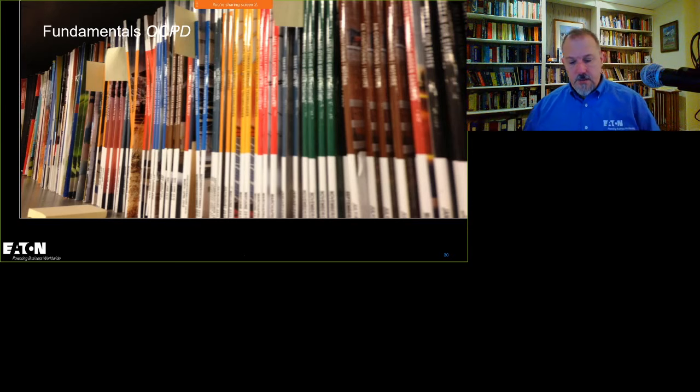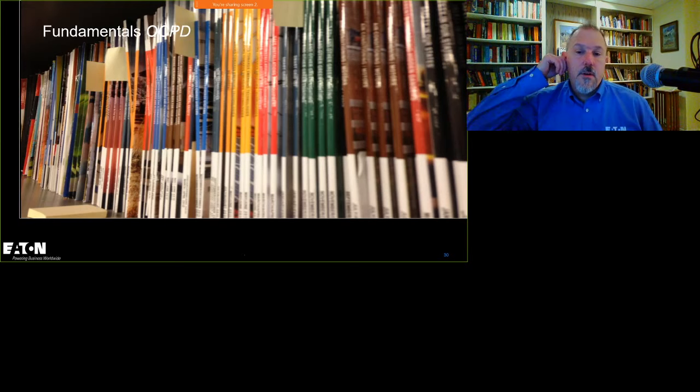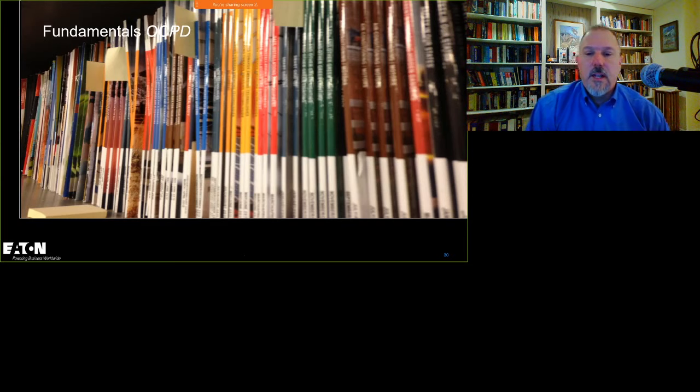A circuit breaker that has restricted access to the adjustment means is permitted to have an ampere rating that is equal to the adjusted current setting. Restricted access shall be achieved. I think I know where you're going, Dawn. I think that's you, Dawn. You still make the setting match the next standard size, or must I match the setting to the exact conductor ampacity? The code says you can go to the next size up. So you can go to the next size up. You don't have to match the ampacity.